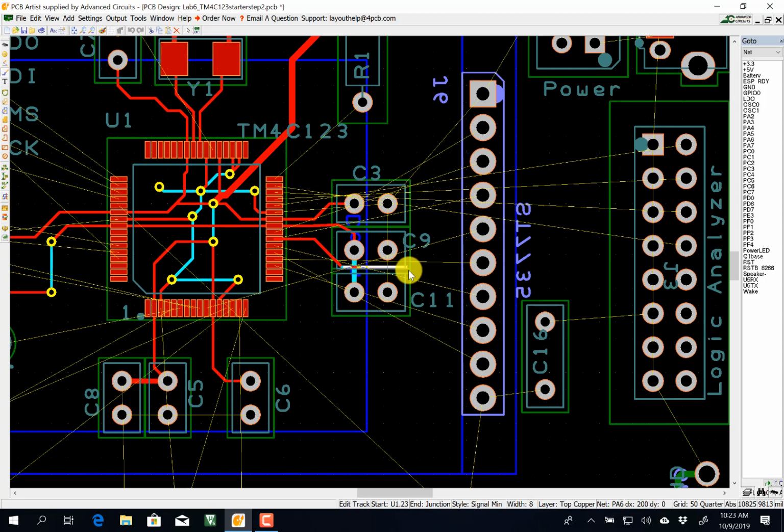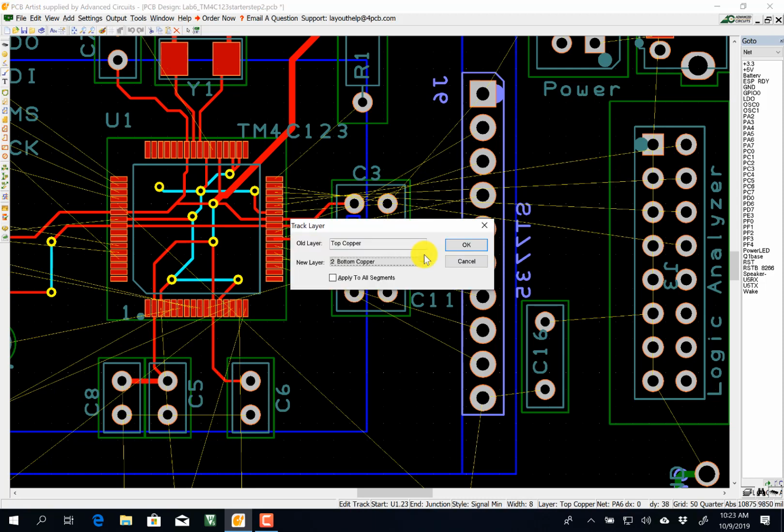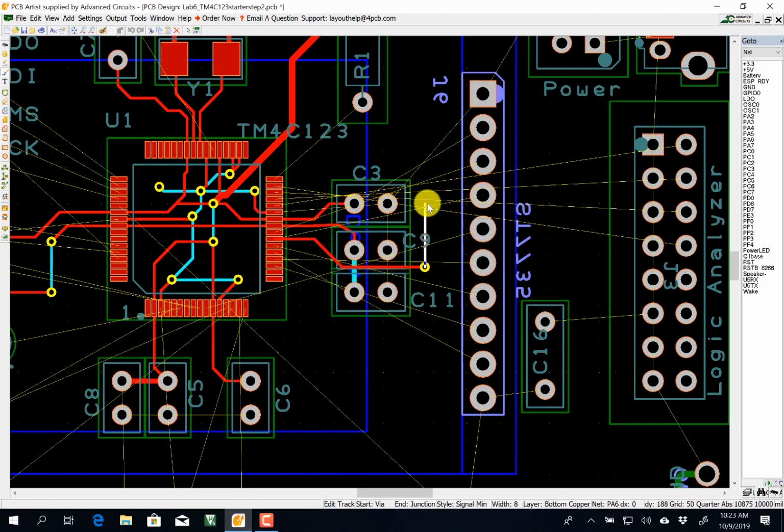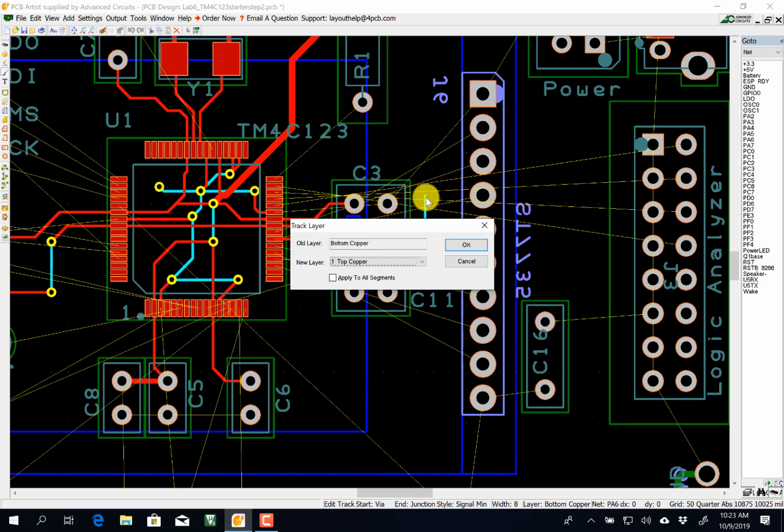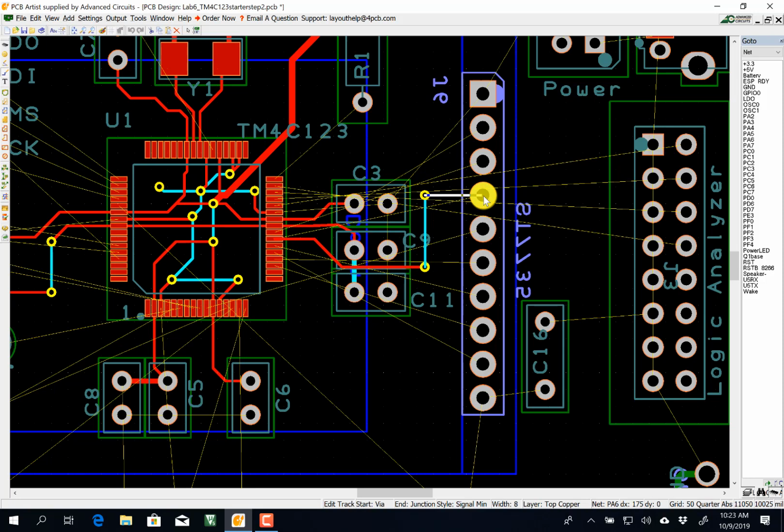Okay, where I'm supposed to end up. Okay, and that is, I'm supposed to end up there. And so when I go up, I'm going to change layers. That's an L. I'm going to be on the bottom. I'm going to go here, change layers again, and I'll be on the top. So in general, I'm going to go right to left on red and up and down on the bottom. Okay, so there's one. Now, if I had missed a track, it would have given me an error.